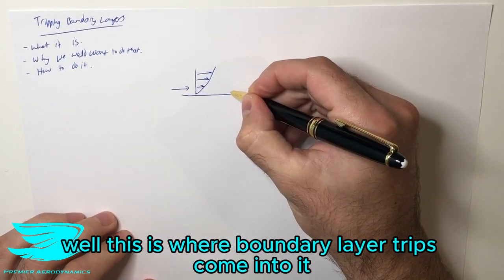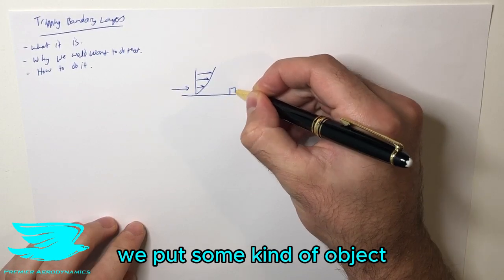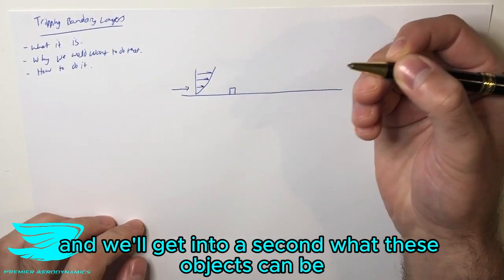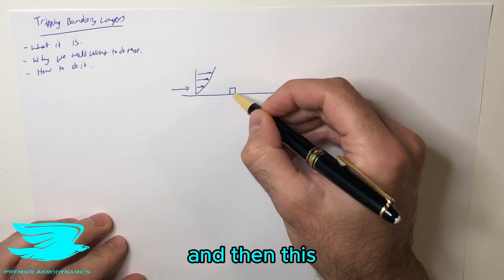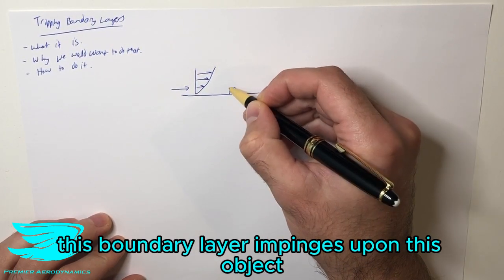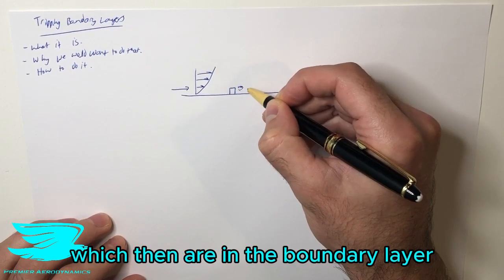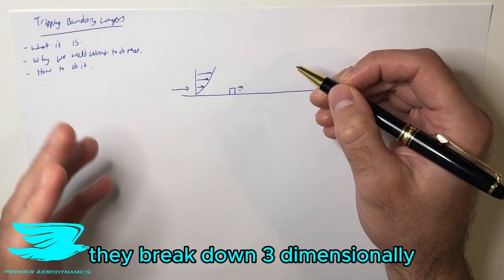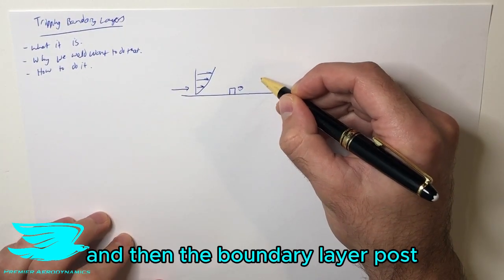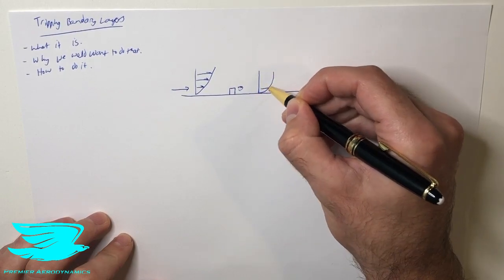Well, this is where boundary layer trips come into it. What we do is on this surface, we put some kind of object, and we'll get into what these objects can be, the shapes of them, for example. Then this boundary layer impinges upon this object and introduces a lot of turbulence. So we get a lot of vortices coming off here, which are then in the boundary layer. They break down three-dimensionally, and then the boundary layer post obstacle here becomes turbulent.